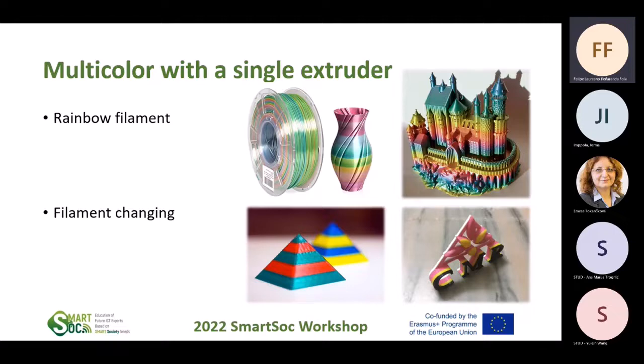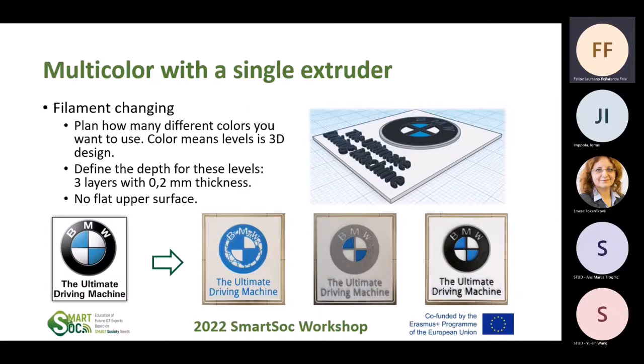So in this case, when you design your object, you have to think in advance that the width of different components should be different to ensure that the last color won't obscure the previous color. Okay, so this is a quite nice technology, but you have to keep in mind when you are creating the design during the modeling.